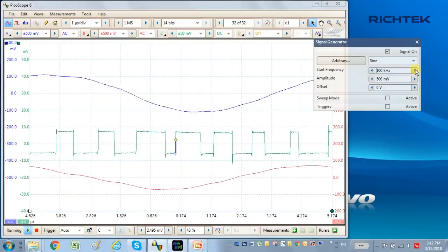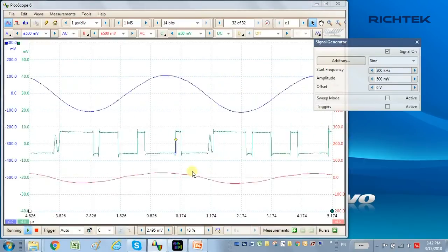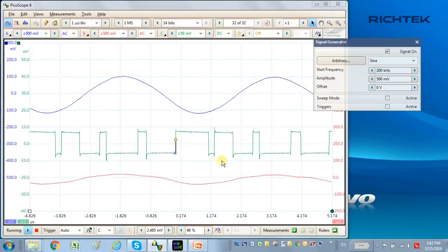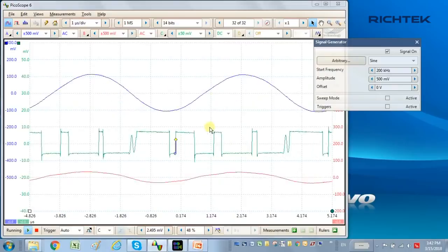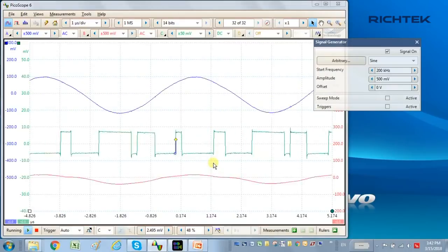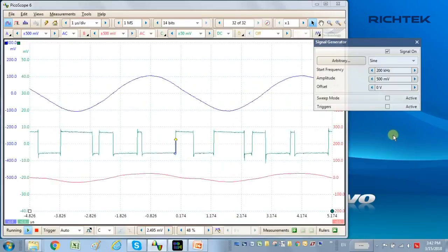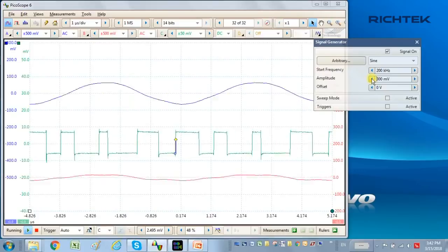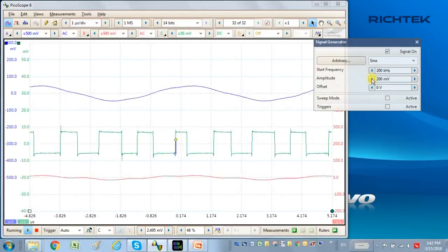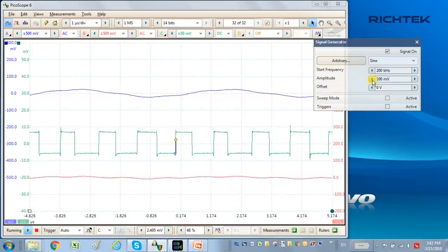At 200 kHz injection frequency, you can now see that the switching signal duty cycle shows extreme fluctuations, hitting minimum and maximum duty cycle limits, and at some points the converter even goes into discontinuous mode. For accurate gain phase measurement results, the converter operation must stay within its linear operation range over the entire sweep frequency range, and should not switch from one operation mode to another.